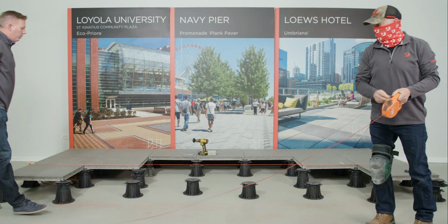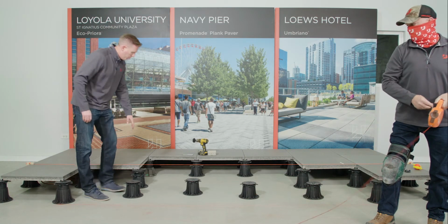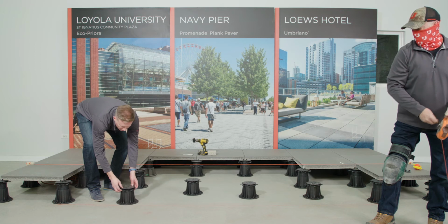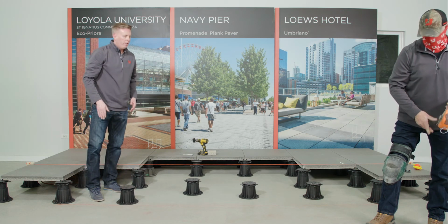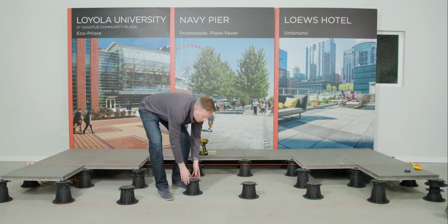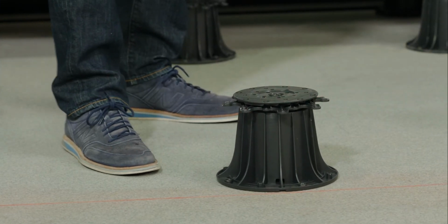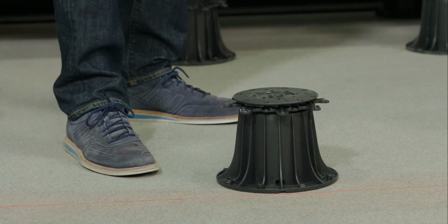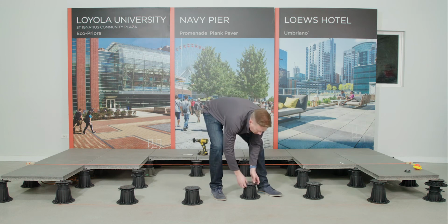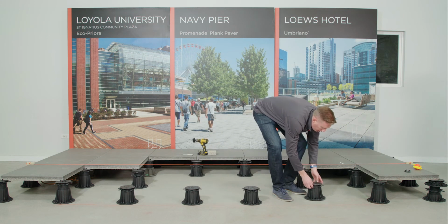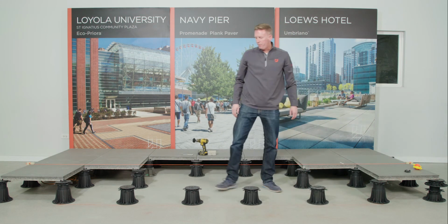And what you're going to do here is you're going to visually line this up with the adjacent pedestal, and you're just going to slide these up so it touches the chalk line. This is going to help you get a good straight line, so when you start to bring the slabs over and set them in place, you only have to adjust them horizontally. It actually helps out quite a bit to get this installation moving much, much quicker.